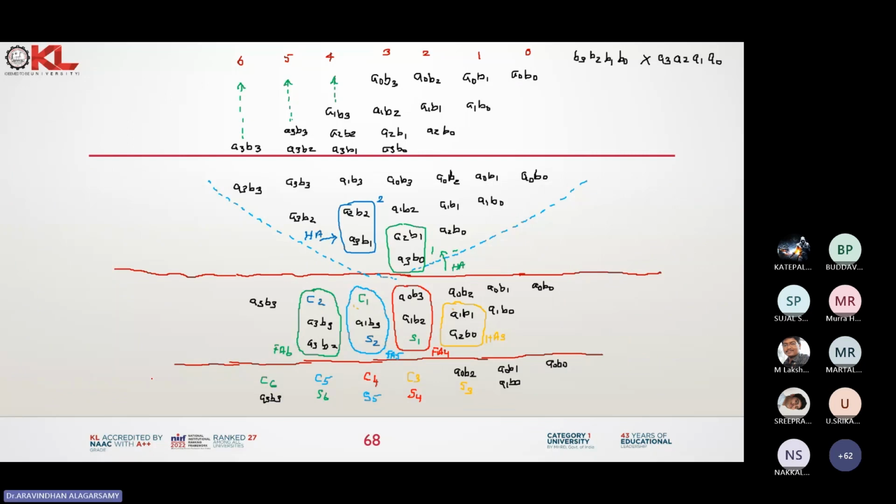Right. Now, after writing this, I hope all of you wrote this without any doubts. Now, let me combine the remaining things. What was this? These two? Half adder, sir. Right. We can combine these two as a half adder. What about this? This half adder will have a sum, because HA7 will have S7 and C7. Where will the C7 go?